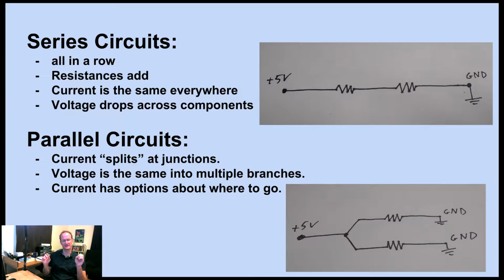And what I've done there is I've written out plus 5 volts. It goes through 2 resistors. Those squiggly lines are resistors. And then it goes to ground. So I've written out G and D for ground. And you can also see the lines getting smaller as they go down. That's the symbol for ground. Those 2 resistors are in series. And so the electricity will flow from the 5 volt outlet through resistor 1, through resistor 2, and then to ground. And that acts like a complete circuit.